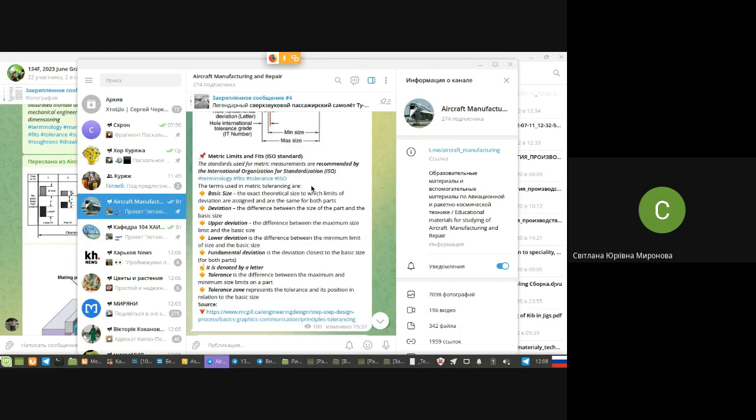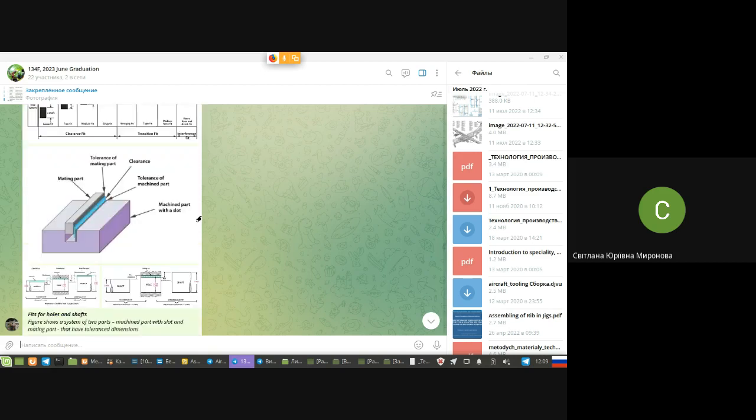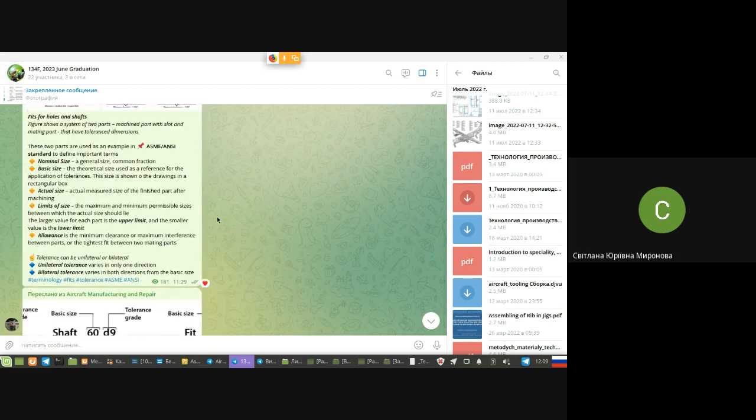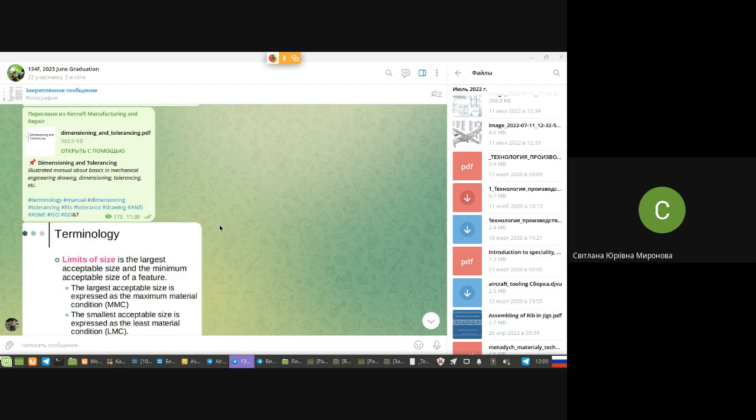They have different approaches to, no, actually it's about the same, and it's rather similar. They have a little bit different approaches to geometrical description, someone includes surface roughness into these tolerances, someone does not include. Practically, that is all the difference. But deviation of sizes, deviation of shapes, deviation of forms, everything is practically the same in both systems. I sent you this to remind you what it is about, in order that you may refresh your knowledge.